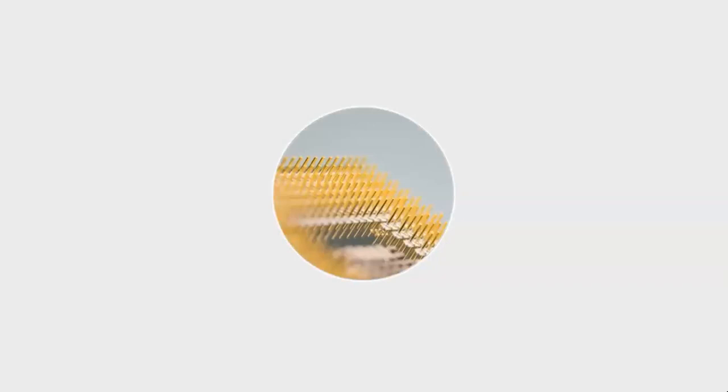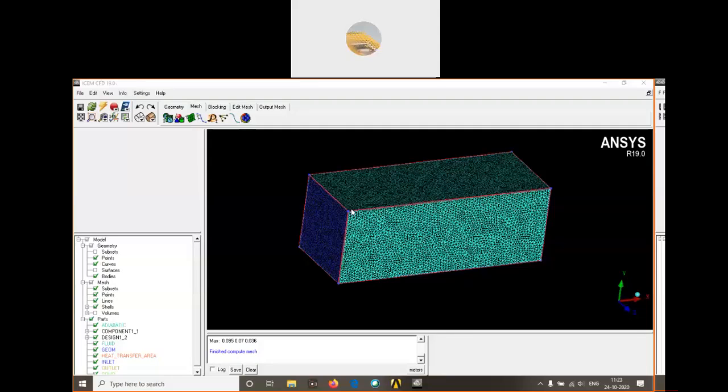See, first we created geometry. Next, we performed some things, naming and all. We exported things to ICEM CFD. Here, we created a good mesh. In the mesh, we have so many things, guys. If you have a notebook, please make a note. Majorly, we have two kinds of mesh. One is tet mesh, another one is hex mesh. I'll even annotate here.